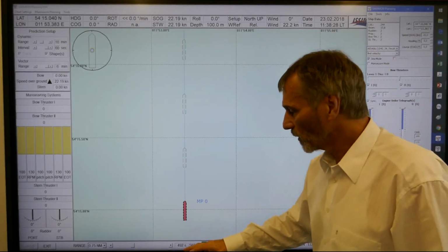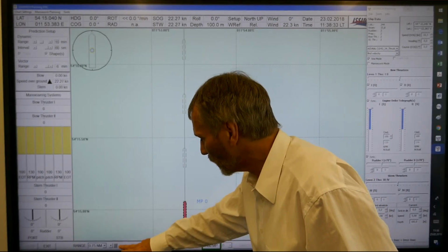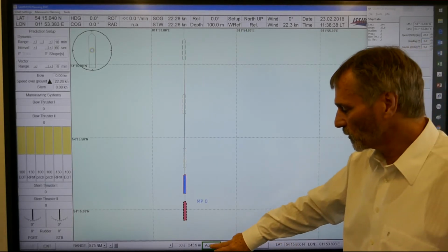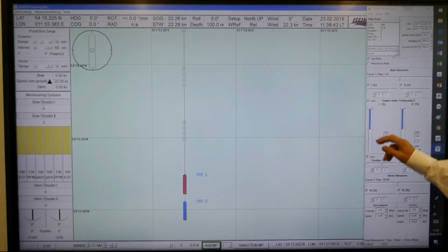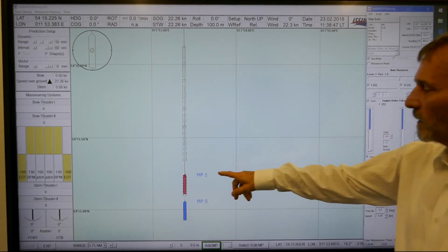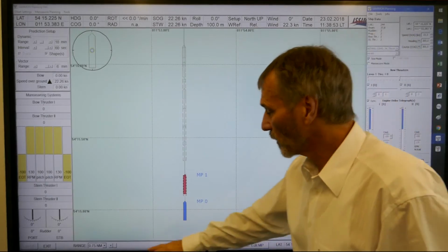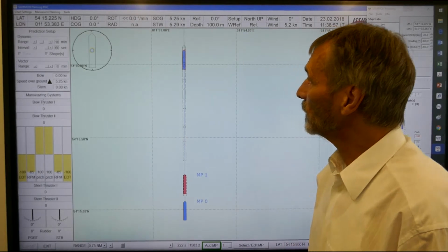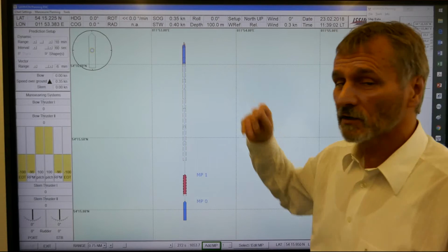And then we move the ship a little bit forward from the initial point, like this here. And then I say, okay, from here I will stop the ship with full astern. So we focus now on this position and we go with the engine to full astern. Then you see the ship will only move until here and then it will stop here. We can check it out. Okay, here the ship has only 2.5 knots if you go a little bit further, so here it's stopping.